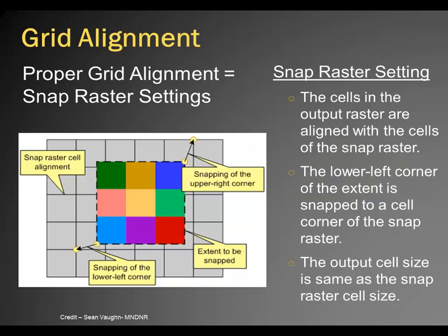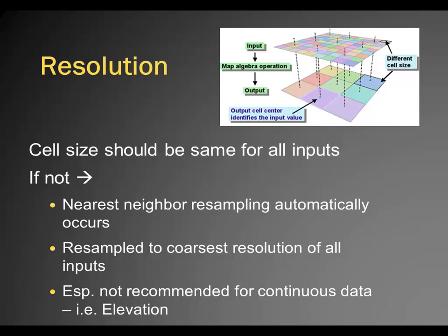The other problem with grids when you're putting these checkerboards together is that they don't line up. So there are processes to go through for the lining up: if they're the same cell size, you can snap the corners so that they line up. Now that's assuming they're the same cell size. If the cell size isn't the same, you have to go through some map algebra process, some raster calculator process, to move from a very detailed checkerboard to a coarse one, or from a coarse one to a detailed one. And that's referred to as resampling, moving from one to the other.